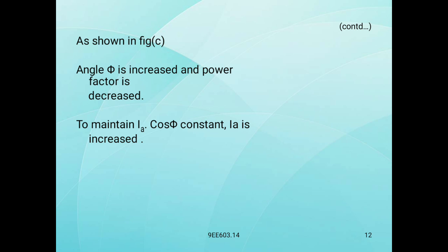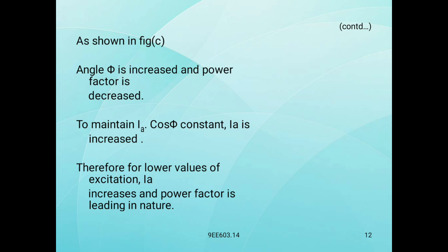As shown in the figure, the angle phi is increased and the power factor is decreased. To maintain IA cos phi constant, IA is increased. Therefore, for higher values of excitation, IA increases and the power factor is leading in nature.